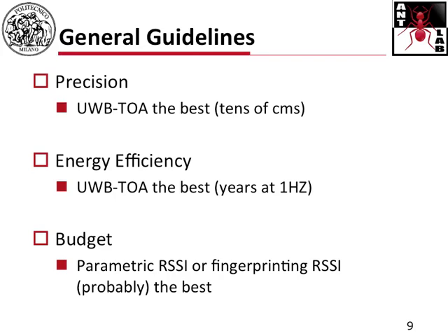What we will do next is basically assuming that we have some type of information on the distance between the tag and the anchor nodes, how this information on the distance, or multiple distances from this tag to multiple anchor nodes, can be used to actually derive the position of the tag itself. Okay, so we will focus on what is called trilateration processes or triangulation processes.